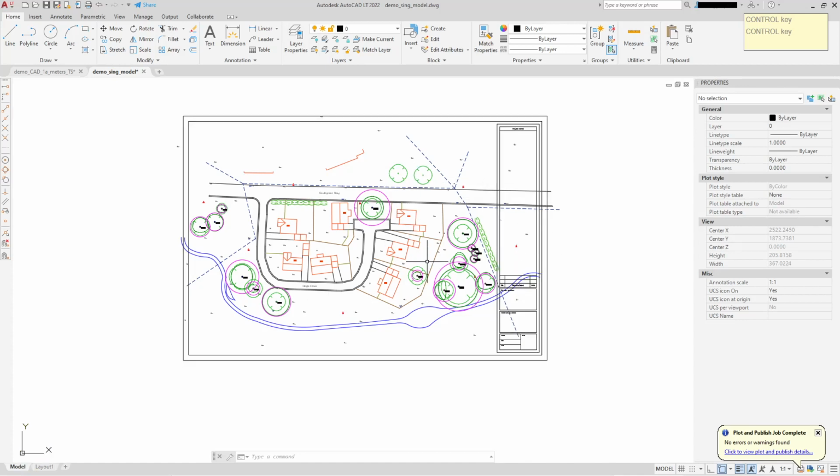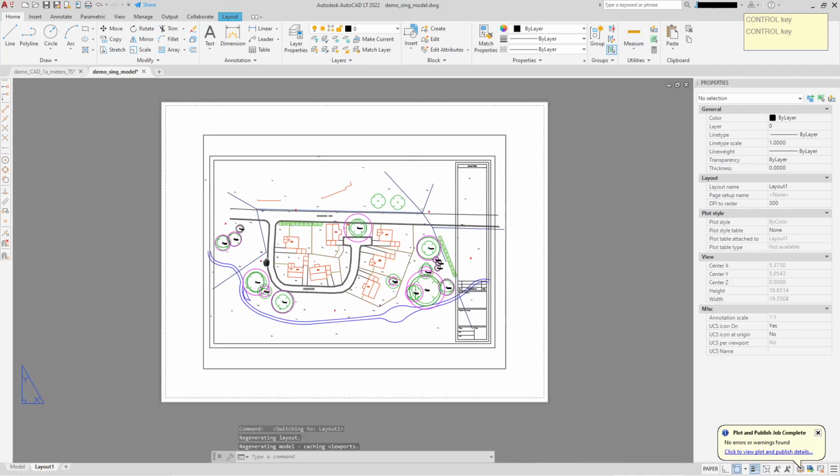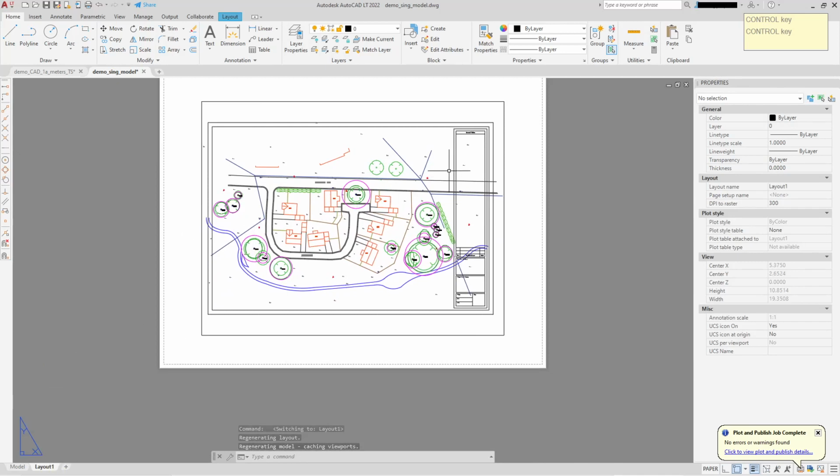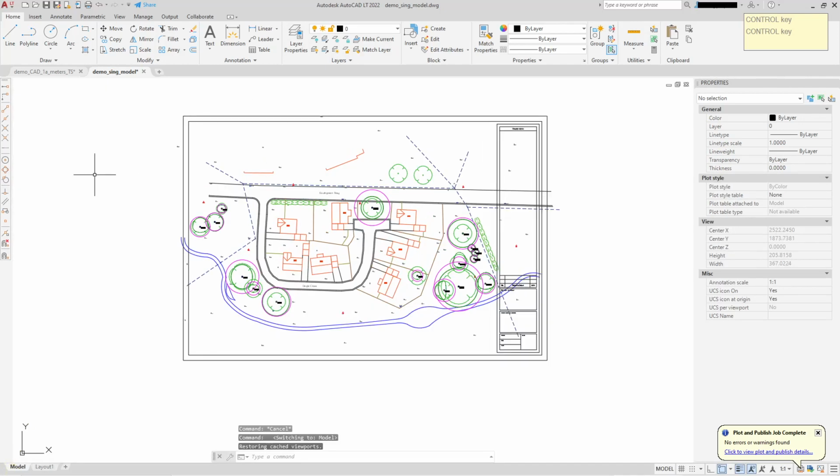If this was a topographical survey, you'd often get the layout stuck on top on model space, and the layout paperspace tab would just be showing model space, but there'd be no setup for printing. They haven't set the viewport up, and they'd basically print from model space.